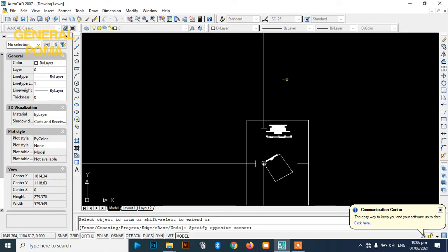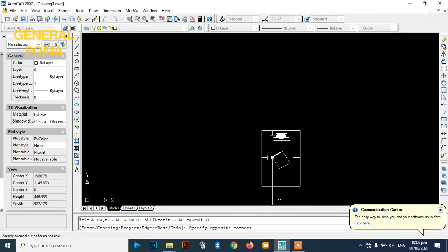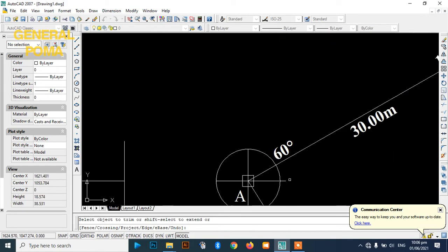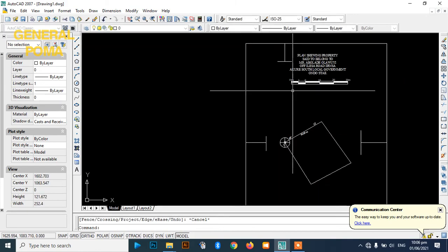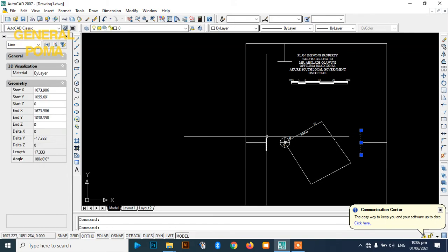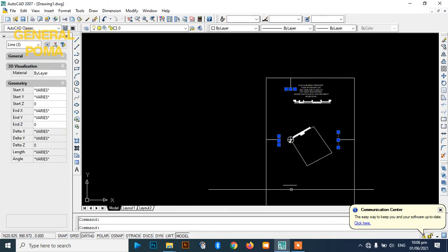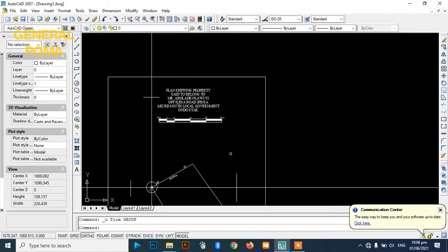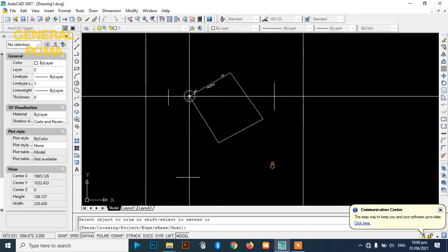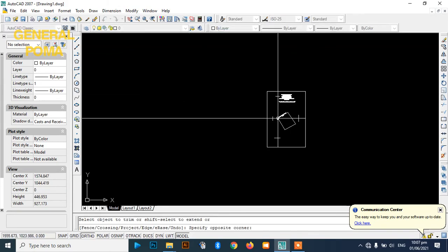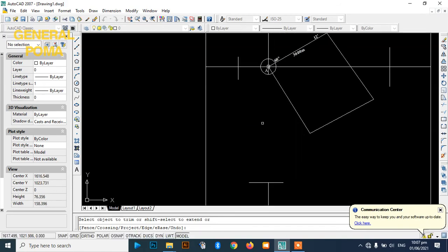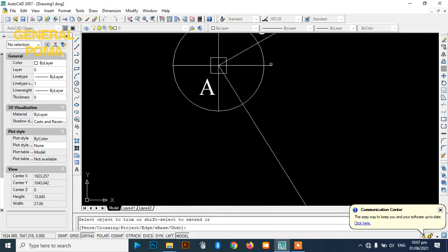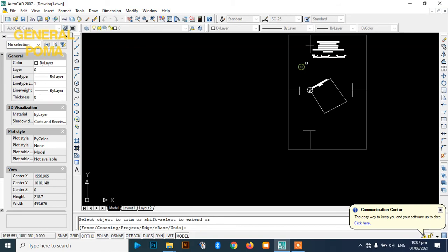And at this point, you can delete the ones at the extreme ends. Then escape. Then you can now click on the line you used to break those points. Oh, I have issues with this one. Let me Ctrl Z, Ctrl Z, Ctrl Z. Sorry, trim again. Then trim this. This also, you can see.